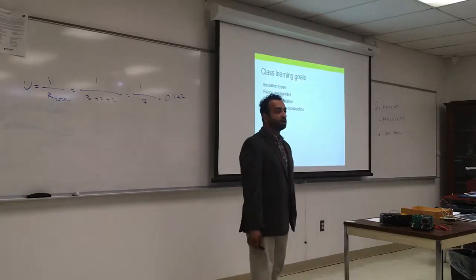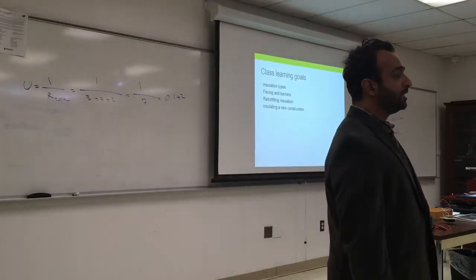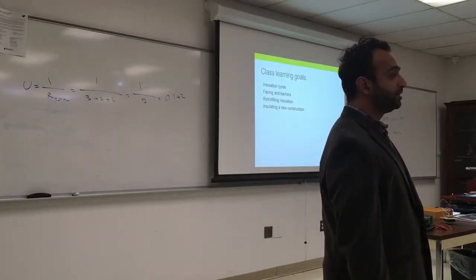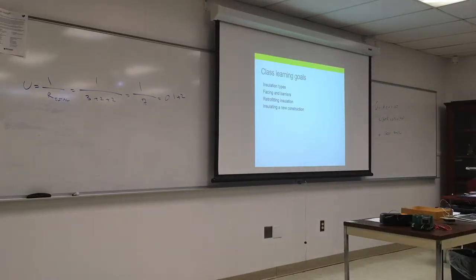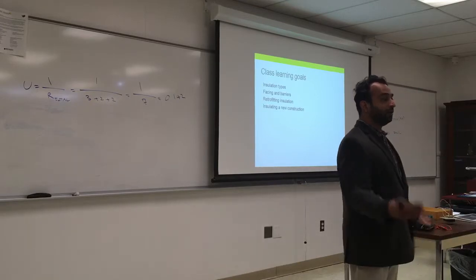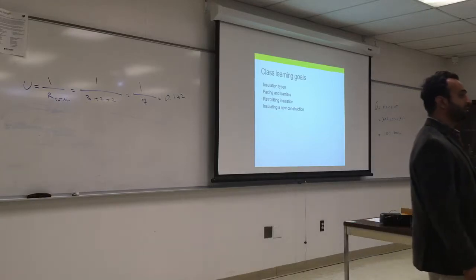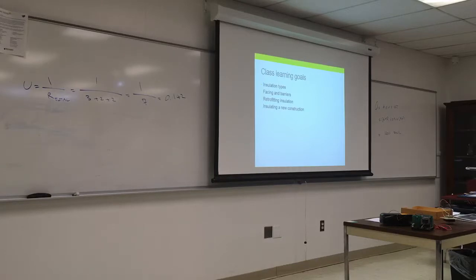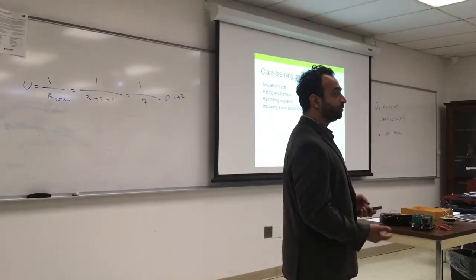Insulating new construction. Now there are a lot of laws and regulations about insulating new construction that were not there like 10 years ago, and you will not get a license for construction, or the house will not be approved, until you get these things done. For example, now by law you have to insulate your basement floor. Once you dig the hole and do the foundation, you have to insulate the entire floor. Why? They have discovered that there are a lot of gases that come from the ground, like radon, that can go into your basement and eventually be bad for you. Radon can cause cancer, and it's a natural gas. So it's really important to seal your house.